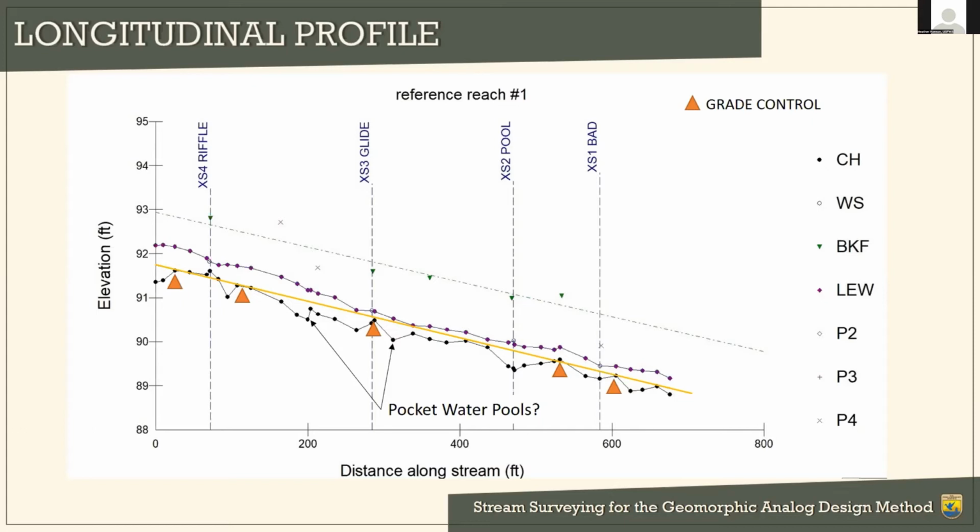Vertical exaggeration is really helpful to see these features. So a lot of times when you do this in CAD, the vertical exaggeration isn't all that much. I really recommend increasing your vertical exaggeration by quite a bit.